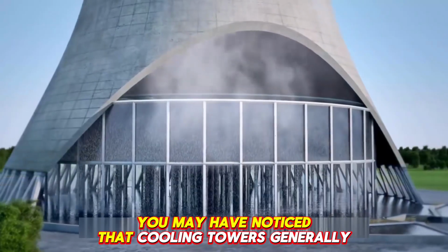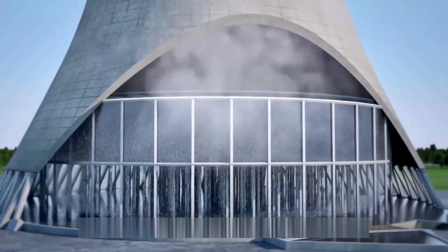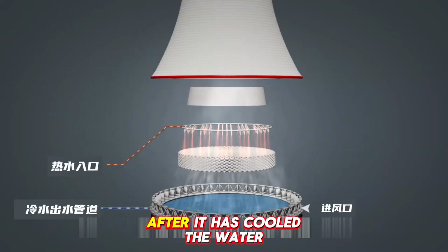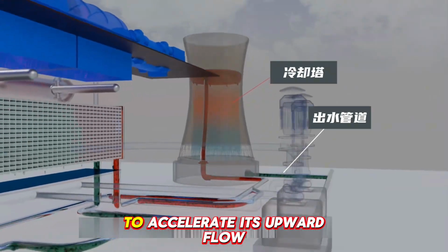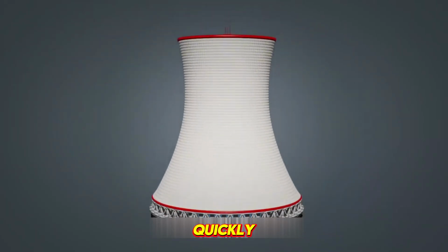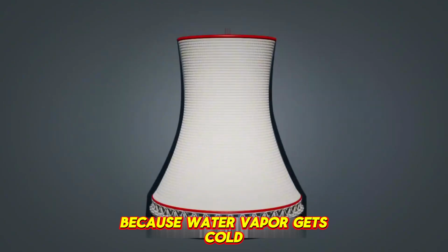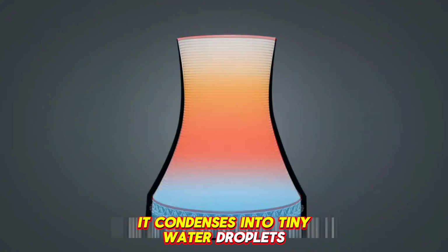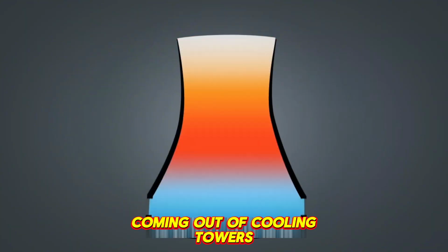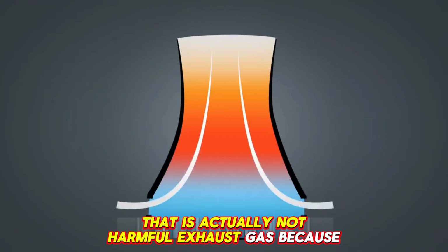You may have noticed that cooling towers generally have this design that narrows in the middle. This design allows the natural air, after it has cooled the water, to accelerate its upward flow, thus carrying the heat out of the tower quickly. Because water vapor gets cold, it condenses into tiny water droplets. That's why we often see large amounts of white smoke coming out of cooling towers. That is actually not harmful exhaust gas.